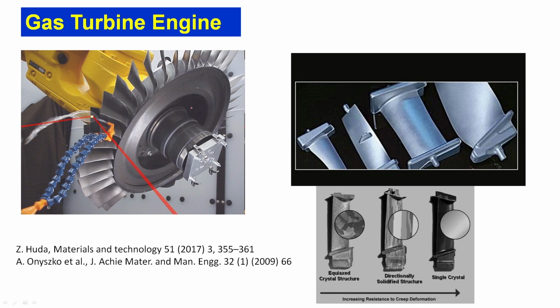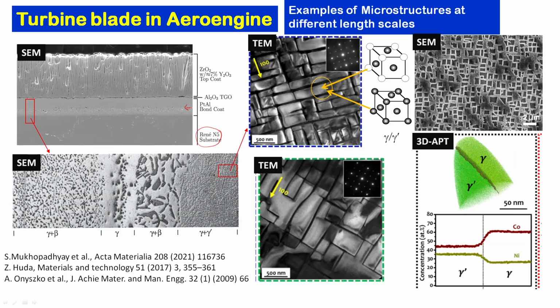They should not get oxidized or affected. That is why you need to put a top layer of zirconium oxide, which has a very low thermal conductivity, and it is directionally grown so that it can retain its insulating properties. But because of the thermal conductivity mismatch between the zirconium dioxide and the superalloy, there can be thermal stresses.